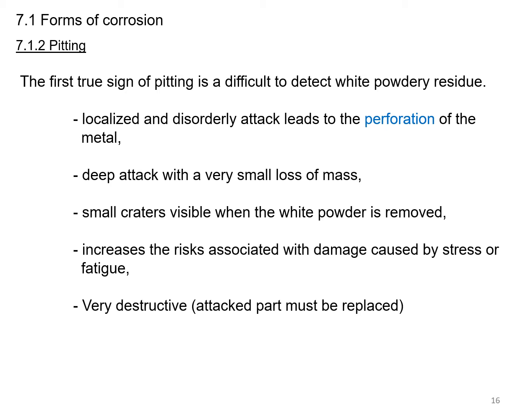It increases the risk associated with damage caused by stress and fatigue because it creates voids inside the metal, sometimes very small, but it can decrease the integrity of the part and can be very destructive. Attacked parts must be replaced. If there's any pitting on a part, there's no real repair for that, so these parts will need to be replaced.